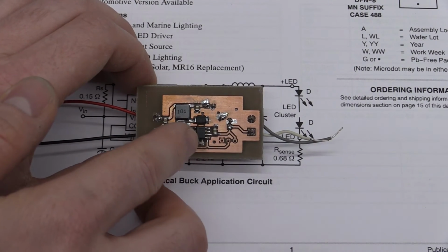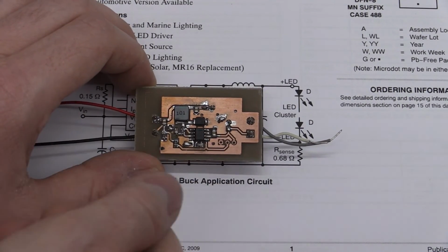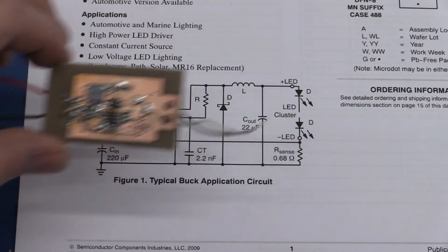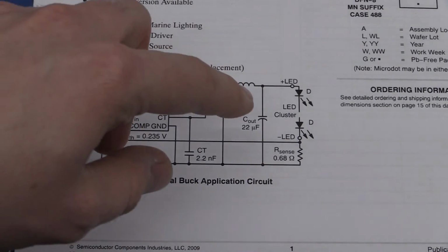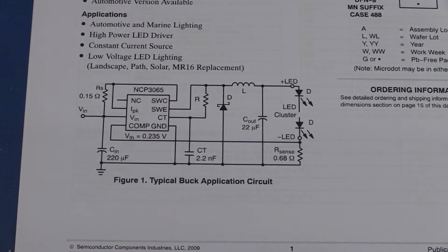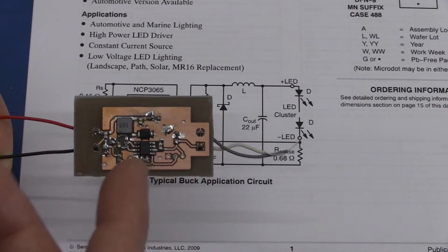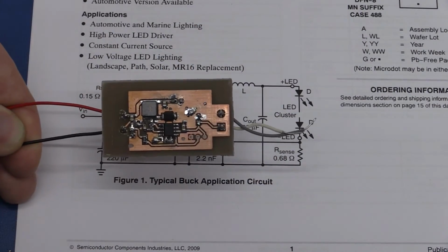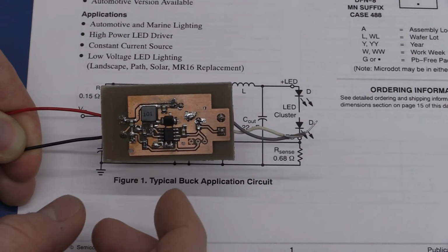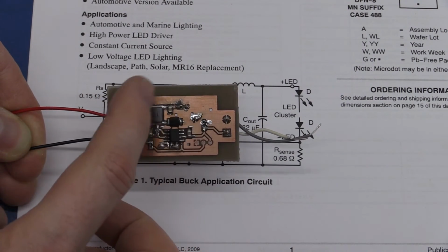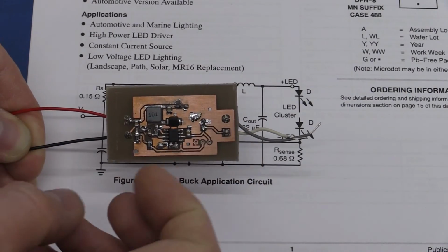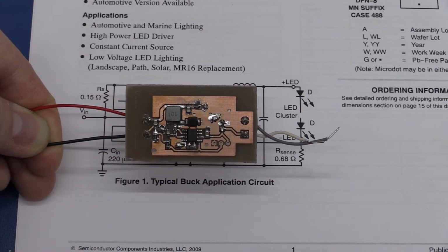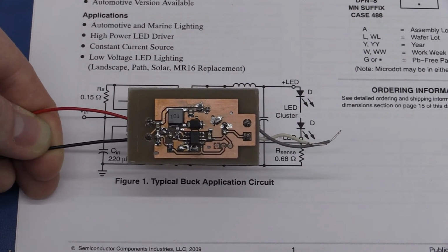I chose the SOIC package because it's fairly easy to solder on a board by yourself, and it's also not as big as a DIP package. You can actually get this chip in a DIP package if you want, but for what I want to use it for, maybe I would like to keep it small. I thought about making some LED lamps by myself, and for that I don't really think I will be using this circuit board. That was just a quick test I made in a few hours just to test the chip.